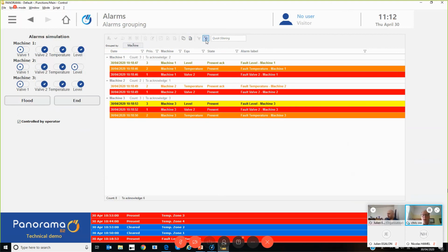There has to be some indication to say, hey, stop what you're doing and go and handle these alarms. That could be another banner, as Julien has suggested, and what we've got at the bottom here. But it could also be flashing icons, which could be related to anything. So you really do need a general purpose part of your HMI to indicate, hey, there are some new alarms, go and deal with them.